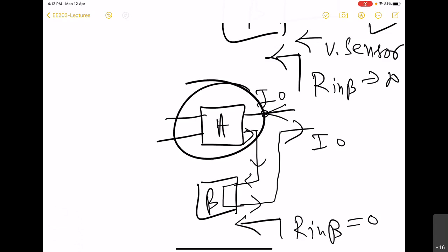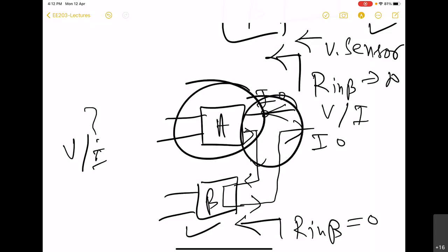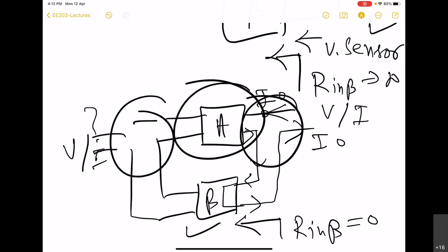It says what quantities can be there on the input side. Similarly, what quantities you can get on the output side. What should be the impedance requirement of this beta network. What should be the topology on the input side, and similarly on the output side as well. So these two quantities, R in and R out of the amplifier, are very important.